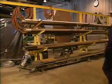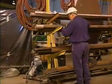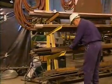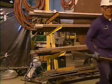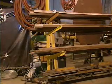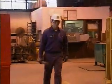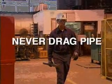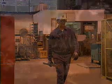Much of the wear and damage looked for during an inspection, such as dents, can be reduced if pipes are handled safely and properly. Handling pipes safely and properly can also help prevent injuries to personnel working with or around pipes. Safe and proper handling of pipes includes the following basic guidelines. Never drag pipes. Dragging a pipe can scratch or dent the outside surface, damage the ends, or contaminate sterilized pipe.